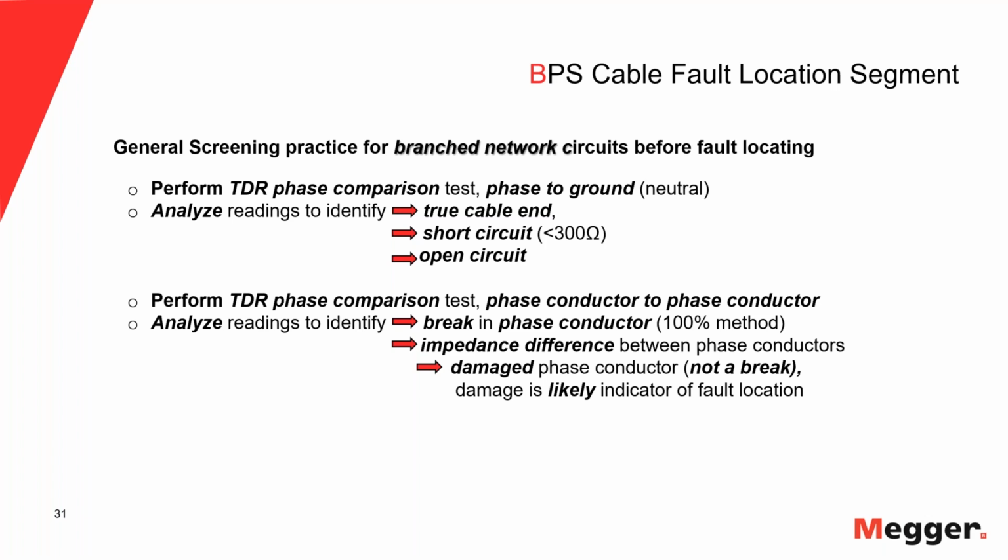So I said, okay, do an insulation resistance test. They did it phase to ground, and every one was low. Then I said, well, do also the phase to phase. Everything was low. I said, that is highly unusual. That almost suggests you have one spot where everything completely blew up and is shorted out to each other. In the end, they went to the substation and found, I think it's called a reactor, right in the substation that had caused a short circuit between all phases.